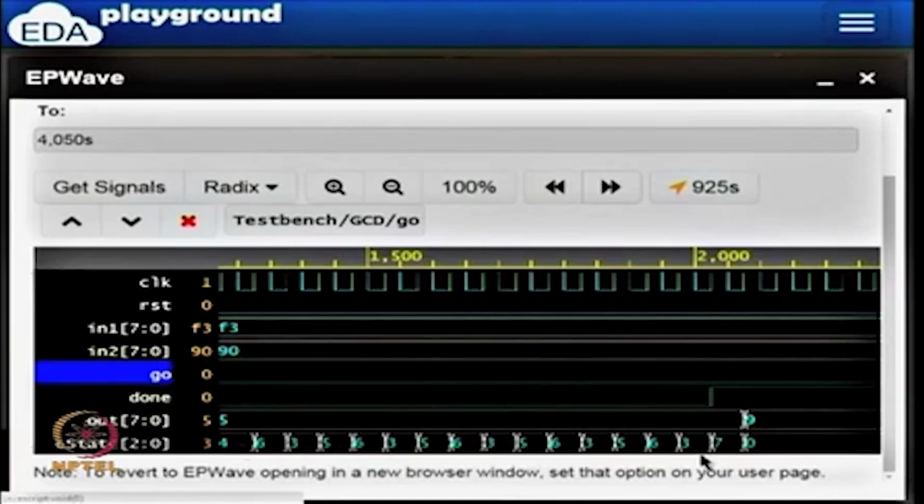So, what we have done is, in this week we have done something very different from the rest of the weeks. First of all, there were no PowerPoint slides. So, you have to see the video to do these things, right. The other thing is, I am going to supply the Verilog files to you. So, if you want to go back and change things and manipulate and so on, you are ready to do it. In fact, I designed what is called a Mealy machine. You can go and see if it can be converted to a Moore machine easily. My suspicion is it is actually easily convertible to a Moore machine. I would suggest that you go and try it, take the Verilog files and play with it.